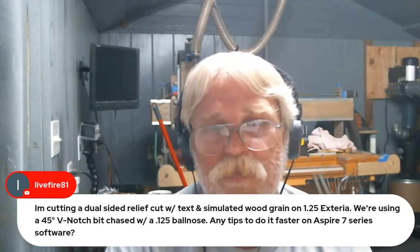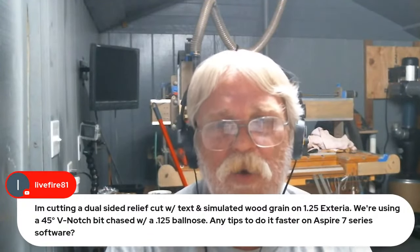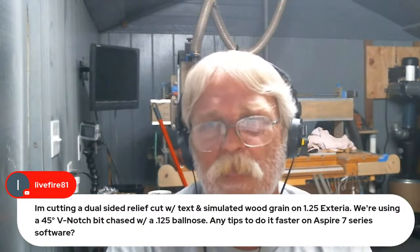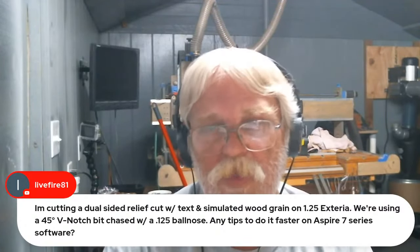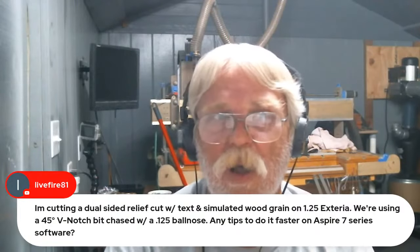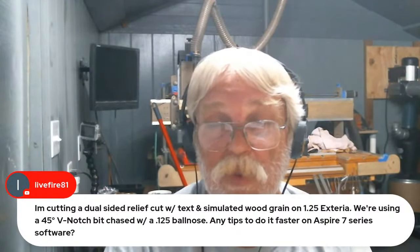Look at your plunge rate. Just look at your plunge rate. And Aspire 7 doesn't have the most efficient tool pathing. You might want to go ahead and upgrade your software to the most recent. I believe